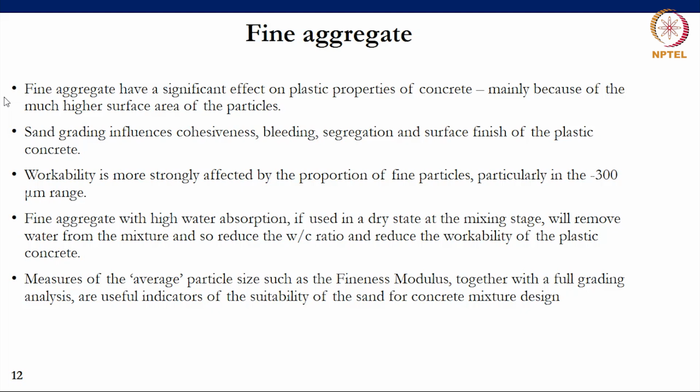The ability to finish the surface depends on the nature of the aggregates and particularly the sand. And this is important in areas like parking surfaces, concrete pedestrian surfaces. Insufficient sand or poor quality of sand will give you a very poor surface finish of the concrete.